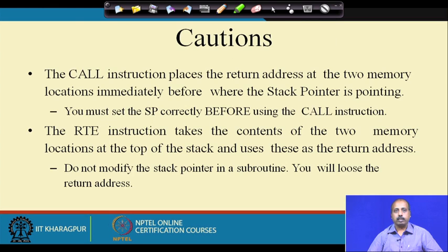Now, there are some cautions. The call instruction places the return address at the 2 memory locations immediately before where the stack pointer is pointing. Some time back I was telling that before starting the actual code of the program, we should set the stack pointer to some proper value.